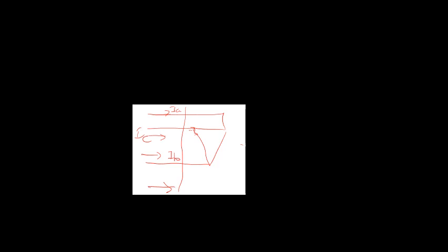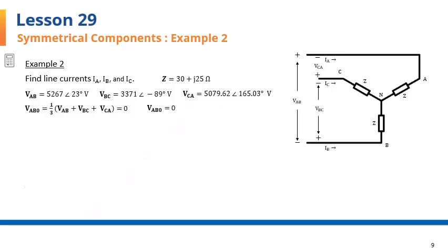That means that their zero sequence set will have components that are all identically zero. Again, we are finding V0 here, but I'll keep the full index as VAB0 so that we can keep better track of the components as they are being calculated.